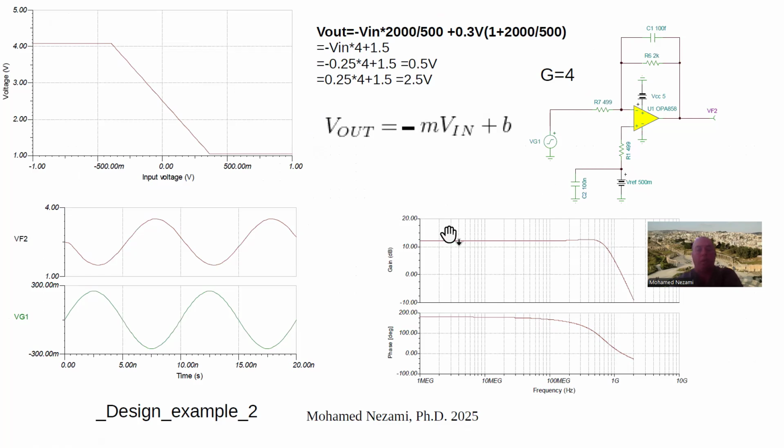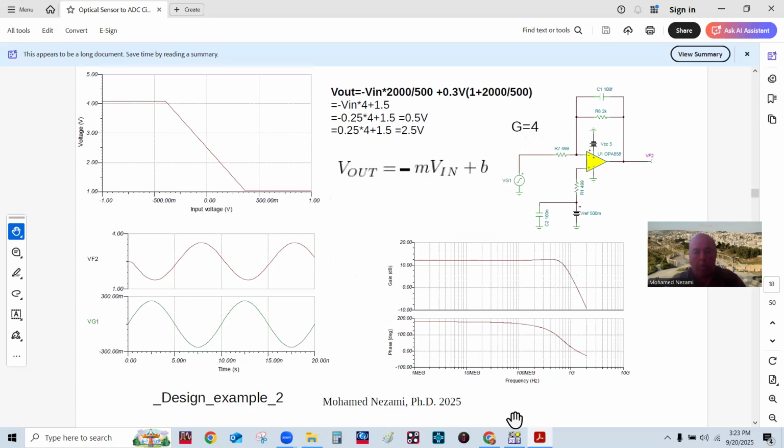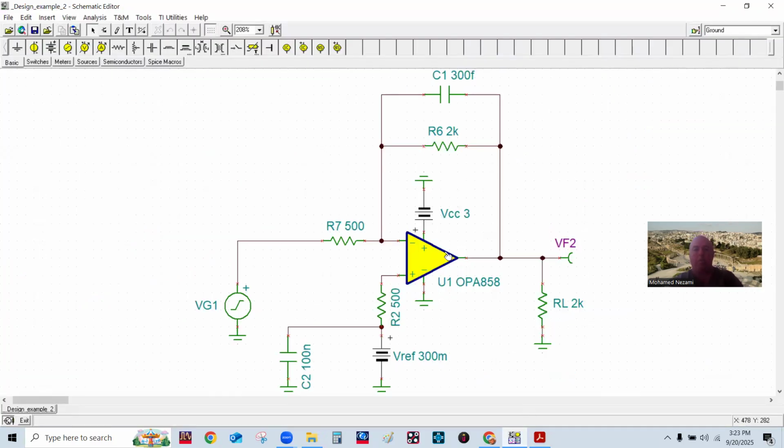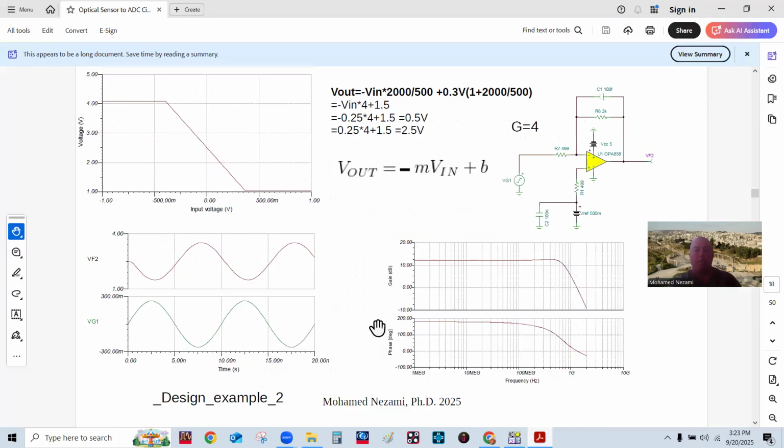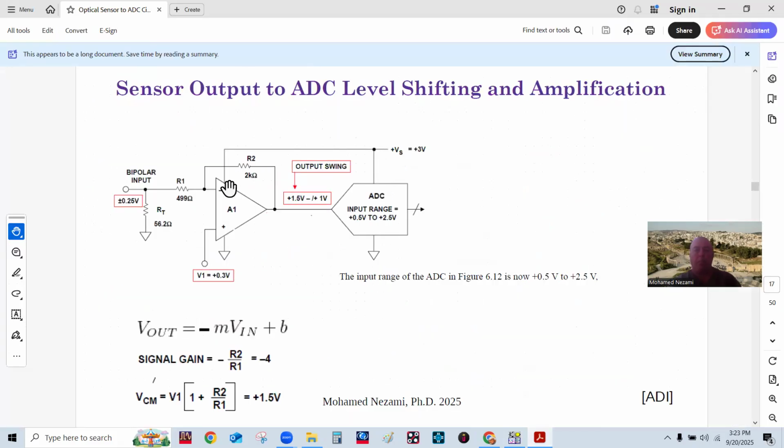So when I ran this, let's show you what happened, and that's why we need to make sure, always look at the op amp that we're utilizing and make sure this guy can go down to 0 volt and go up to 3 volts, as the circuit in here was suggesting, okay? So that we can go within this range in here. This range in here, of course, is from the data sheet, okay? That we cannot do anything about. If we need to vary this, then we have to vary that, okay?